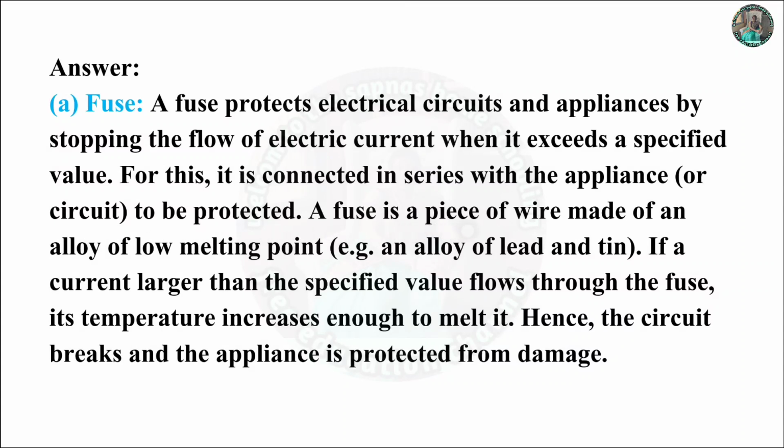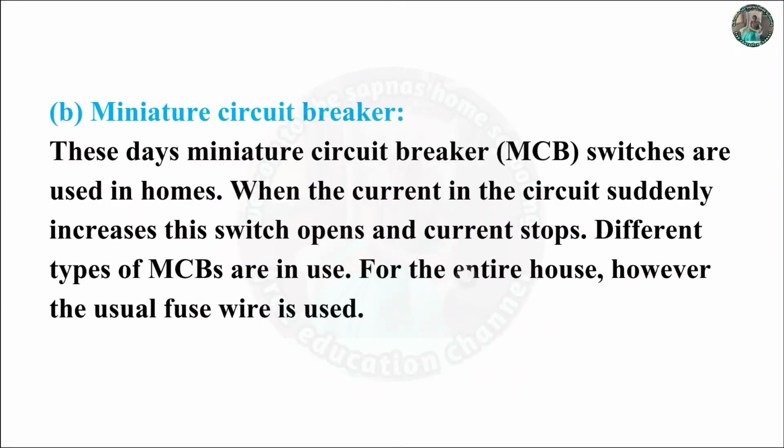A fuse is a piece of wire made of an alloy of low melting point, for example, an alloy of lead and tin. If a current larger than the specified value flows through the fuse, its temperature increases enough to melt it. Hence, the circuit breaks and the appliance is protected from damage.